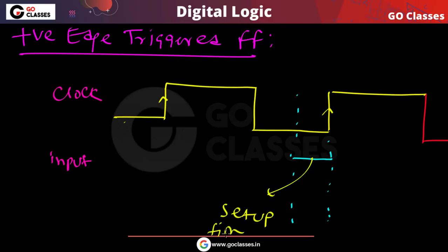This is called the setup time. It means that just before this rising edge comes, for a minimum amount of time, our input must be steady. That is called setup time.